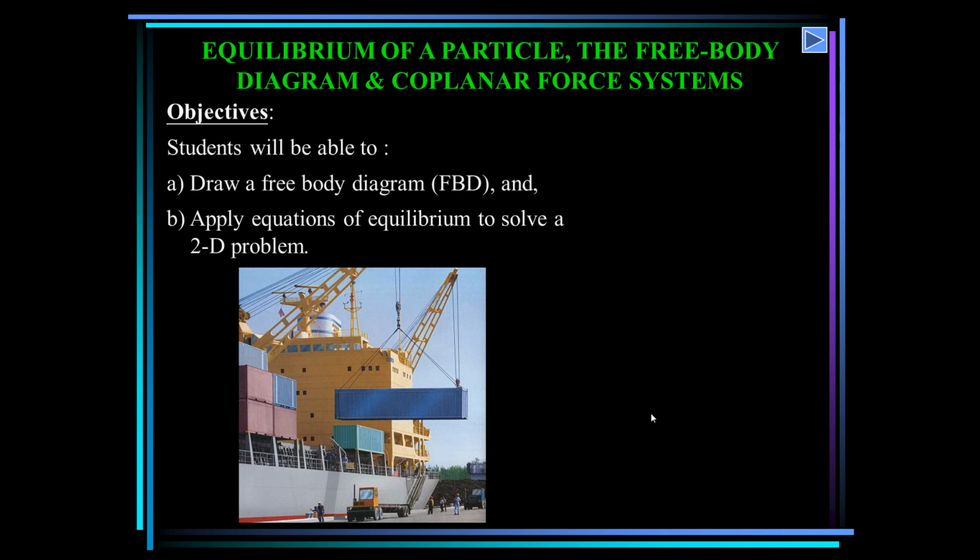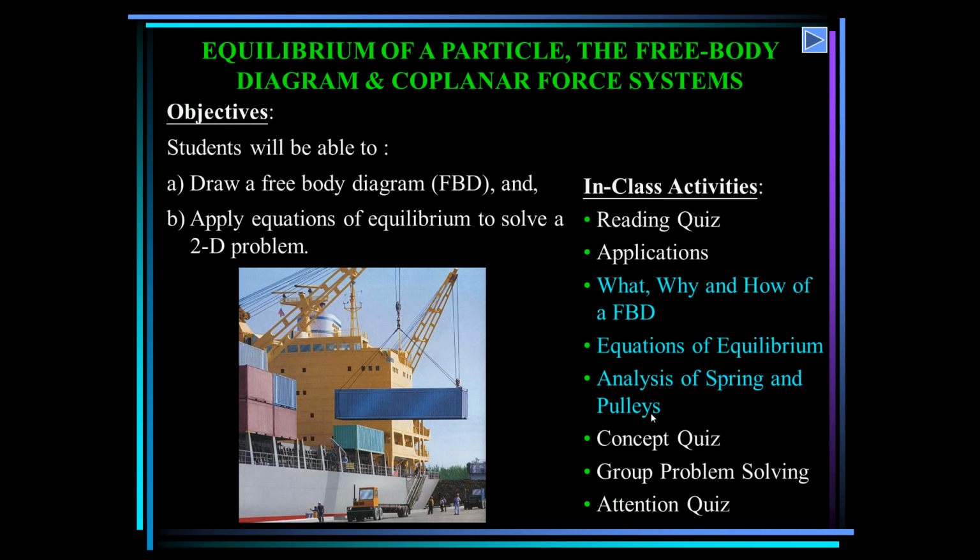Okay, today I will introduce the equilibrium of a particle and the free body diagram, and those forces acting on a coplanar system. The objective in this section is that students should learn how to draw an FBD and apply the equations of equilibrium to solve a 2D problem.